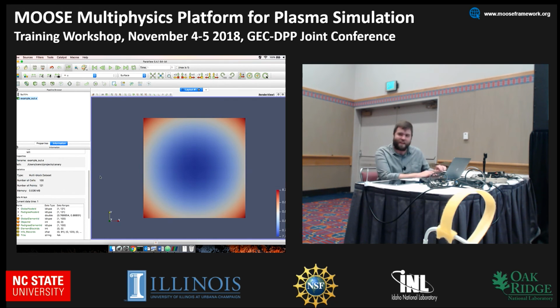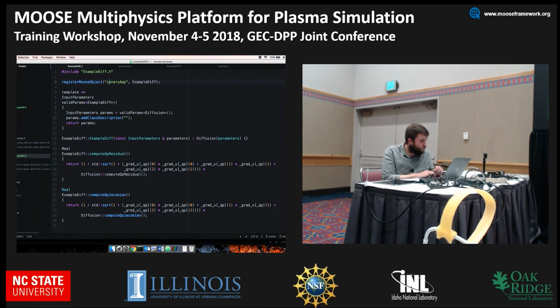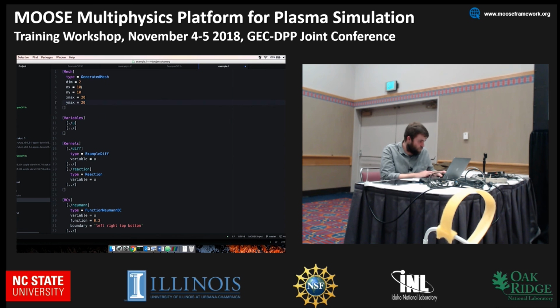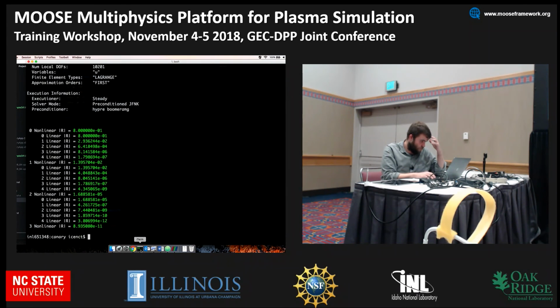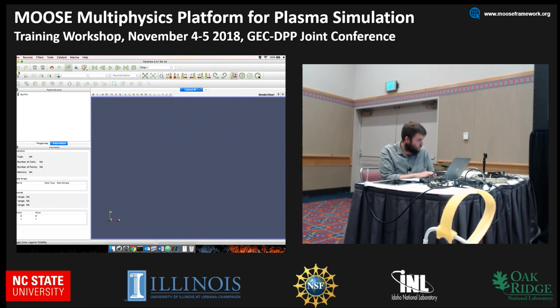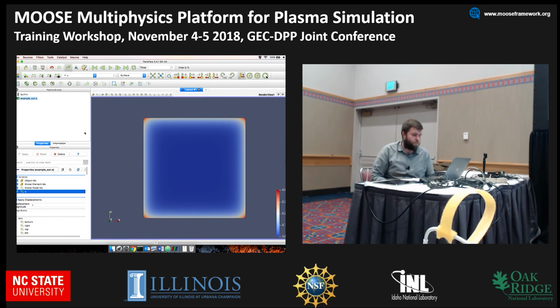So if we make it bigger, it'll probably work. So let's do that. So for a unit square, let's go back to my Atom. And so if we go back and y max 20. I'm just making this and seeing, because your gradient should be different. So then I'll just give it a decent resolution, and then we'll run that again. Now I'm actually going to close this out this time since the mesh has changed, just in case it influences anything. Yep, and there you go.